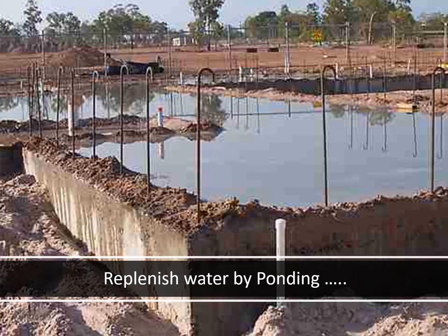This is suitable mainly for horizontal surfaces where you can keep the water in position. In sloping conditions like vertical walls, ponding is not possible because the water will not stay in that position. So this method is applicable only to horizontal cross sections, and the temperature of the water is also important in this case.